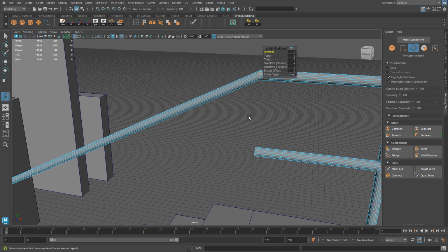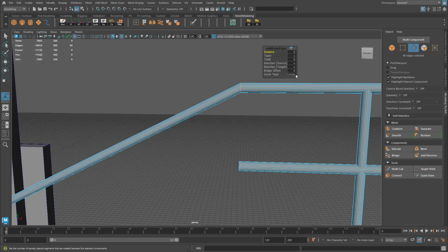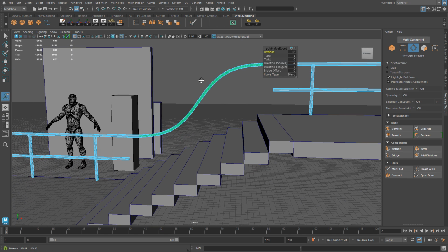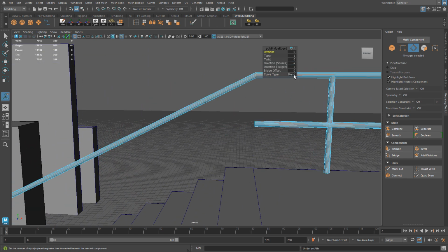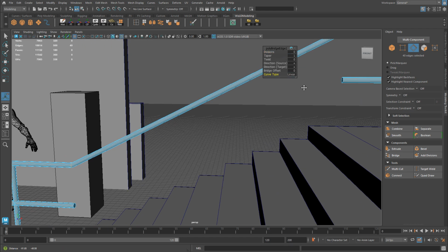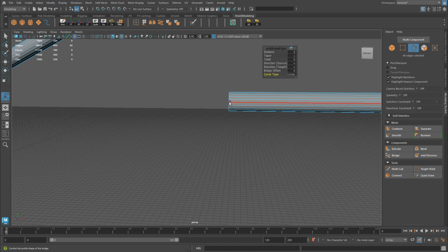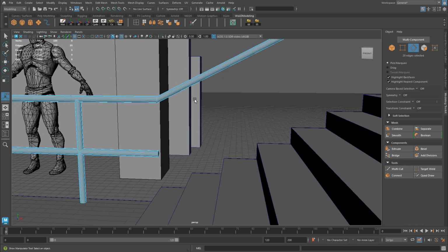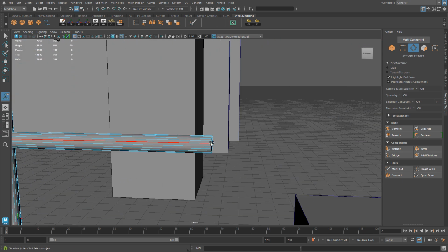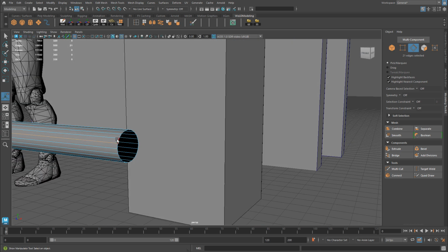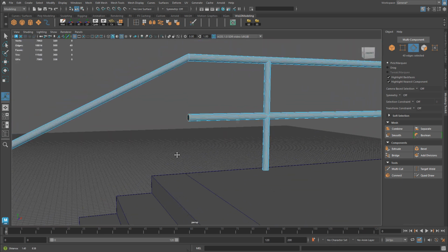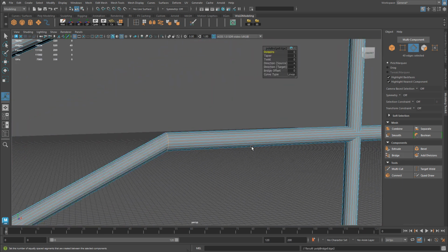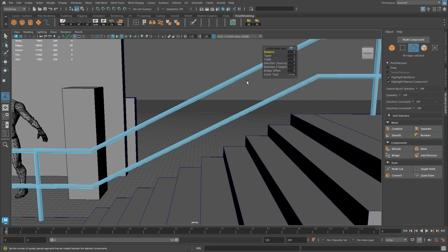And they've been connected. I can take a look at the curve type. I'm going to keep it to linear, but I can maybe add blend. And actually that's not going to work for us. So we're going to keep it at linear with no segments added in between. All right, so we have one connection point made. And now let's go ahead and create a second one. Select these edges, also the ones on the other side. Make sure that I'm selecting correctly. Let me do it again. Now let me check that both sides are selected, and let's bridge. And now we have a second connection point.